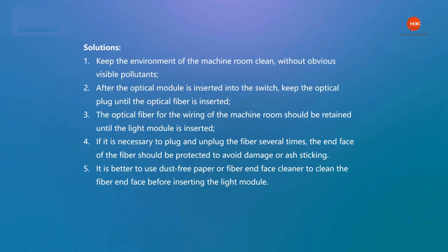inserted. Fourth, during the installation or debugging process, if you need to plug and unplug the fiber multiple times, you need to protect the fiber interface to avoid damage or dust. Fifth, if the interface of the jumper is not protected by a dust cap, before inserting the optical module, it is best to clean the interface of the optical fiber with dust-free paper or a fiber interface cleaner before inserting